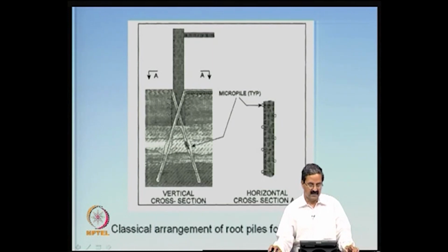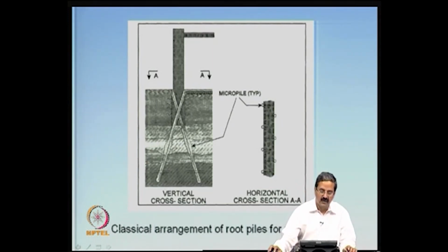So to some extent, some load on the foundation is resisted by the grout interface force, and this is an advantage. You need to know how much force is to be resisted by the grout, that is, the skin friction resistance along this material.